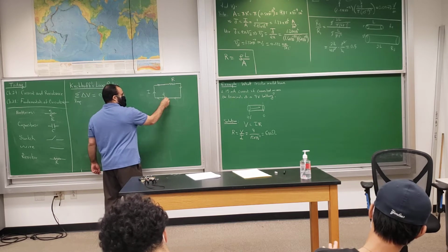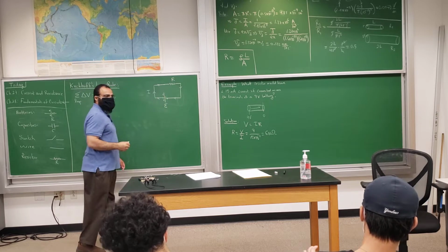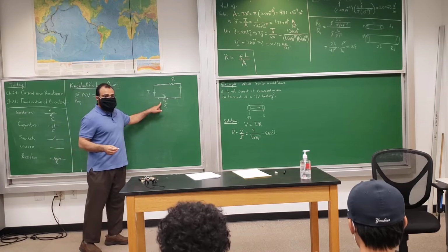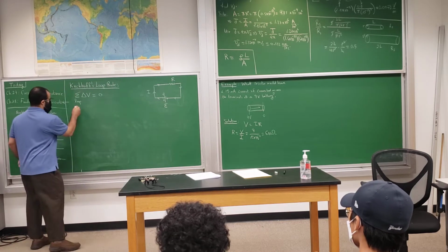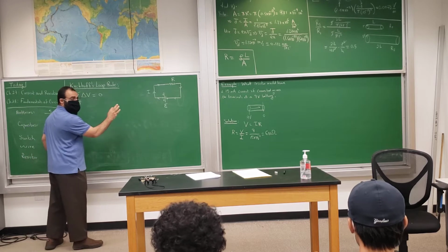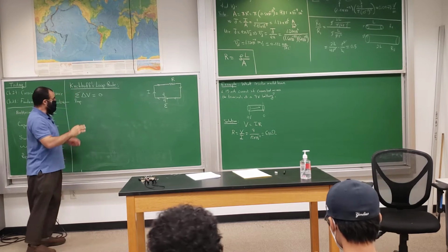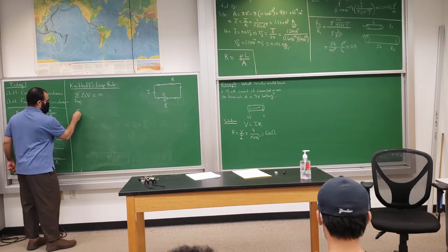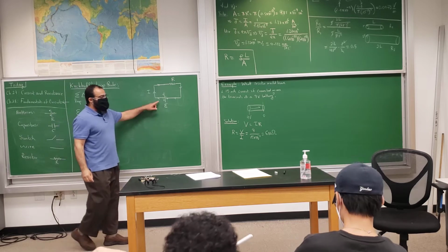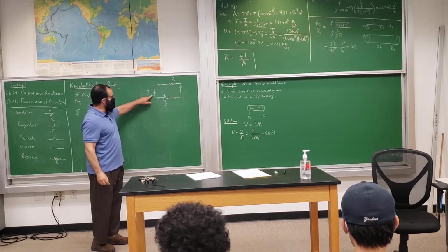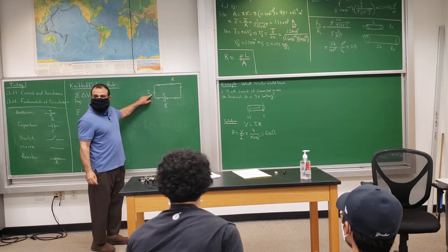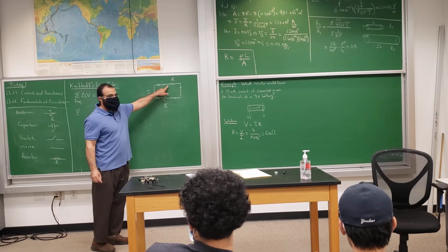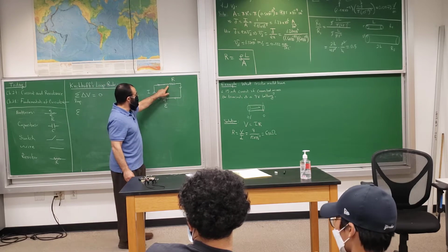When I go from here to here, I went from minus to plus, so the potential difference, the change in voltage is just the voltage of the battery, the EMF of the battery, so you get this. So what I'm going to write is specific for this circuit, not for every circuit. This is for all DC circuits. Here is what I'm going to write. So you get EMF. We're going to follow the current. These are wires. Is there a potential change on the wire? No, there isn't. So the wires is no potential change, so nothing.